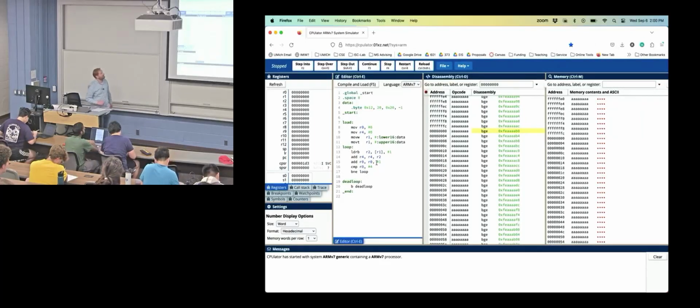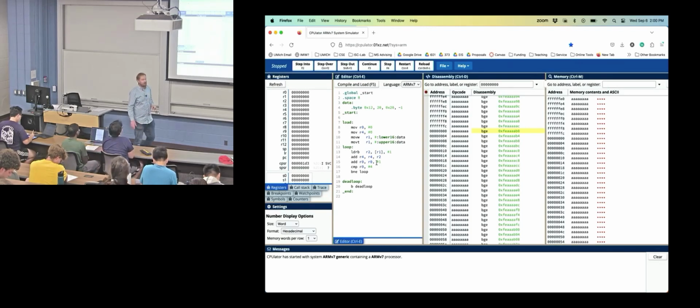All right, so here is an online ARMv7 simulator that kind of works. It's not exactly STM's flavor, but it will do everything correctly if we don't look too hard. We have our code. We'll show the disassembled file, and then we're going to show memory locations. Normally every line is 4 memory locations, or 4 32-bit words. I've just broken it out to 1, so each one of these is incrementing by 4. Okay, so there's the code.